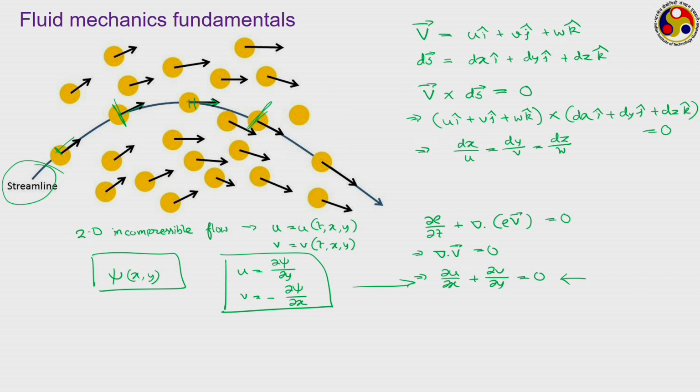So, the stream function psi is defined with this particular definition of u and v. Now, let us write d psi, the change in the value of this psi, which is referred to as the stream function. But so far we have not related this one to the streamline. This is completely an unrelated concept till now. This is just a definition of a parameter psi which will satisfy the 2D incompressible continuity equation, and therefore, instead of using u and v as two different dependent variables, we could have used just a single variable psi, as u and v can be defined in terms of psi itself.